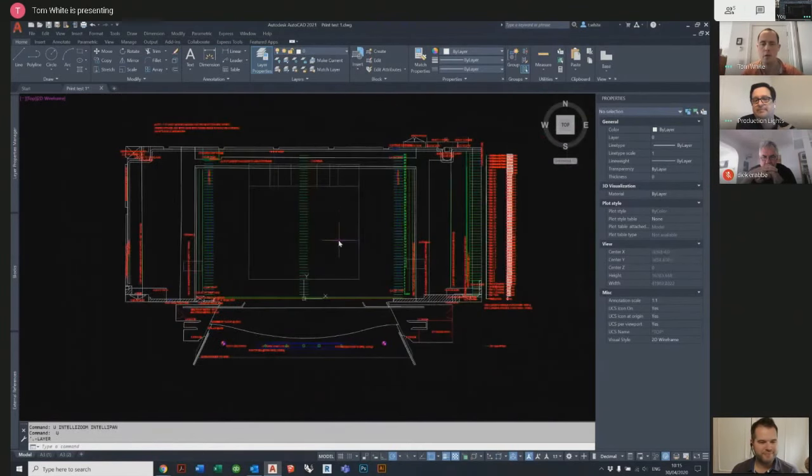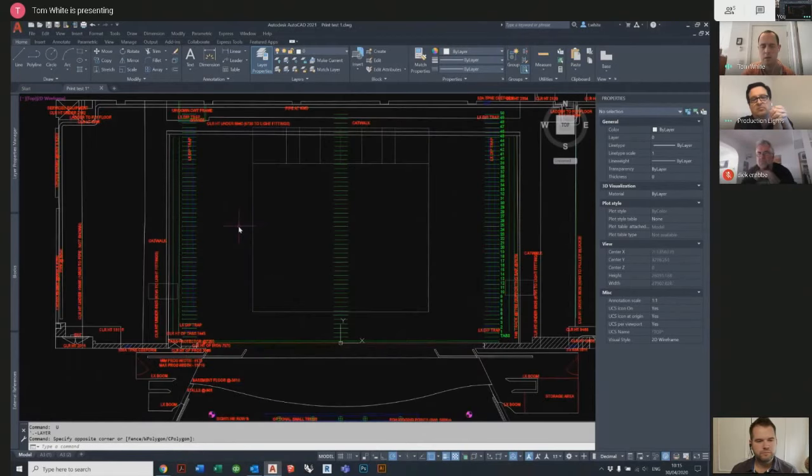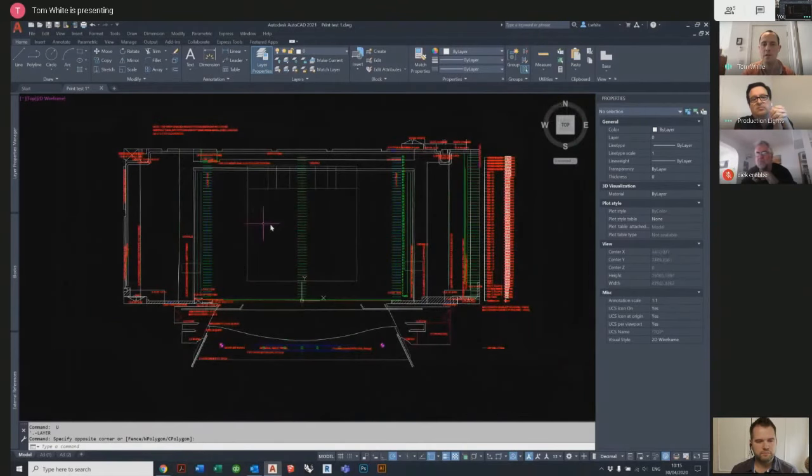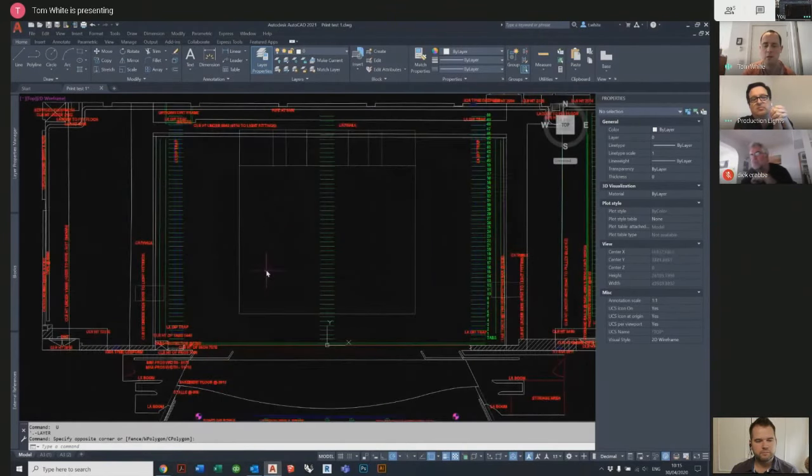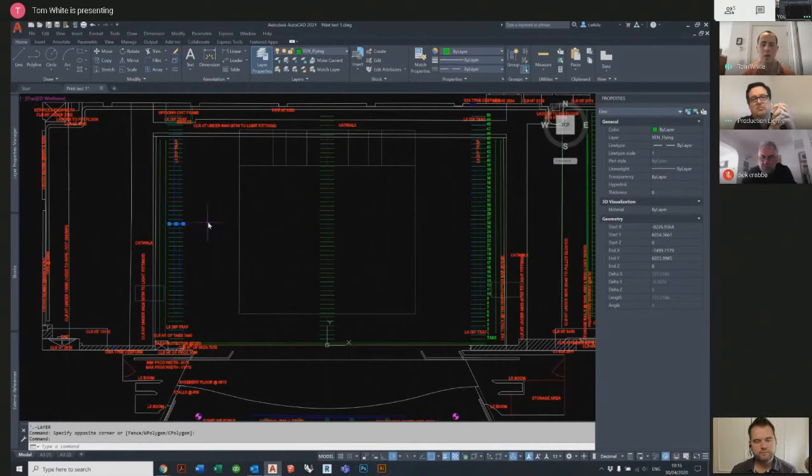Perfect. So another thing, depending on how far in the future the meeting is, another quick check, just in case the job does become real, is I just want to check whether it's a real 2D drawing or whether it's a 2D-looking 3D drawing, which by total accident is super easy to do. Some of these lines have a Z value which is not on this black area. This black area is 0, and so all these lines should have a Z value of 0, i.e. they're not extruded, they're not floating off the ground.